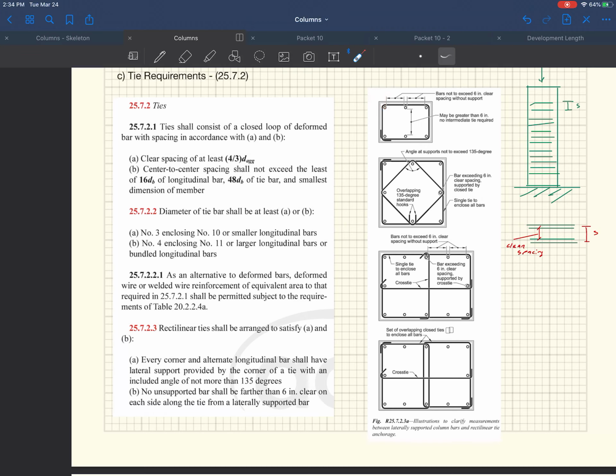And so if you think about this thing wanting to buckle out, right? It can't buckle out because there's rebar and tension around it. Okay, right? This thing wants to buckle out this way. Well, this bar right here is resisting it. And then same thing on this side. If it wants to buckle out this way, it can't because this piece of rebar is loaded in tension.